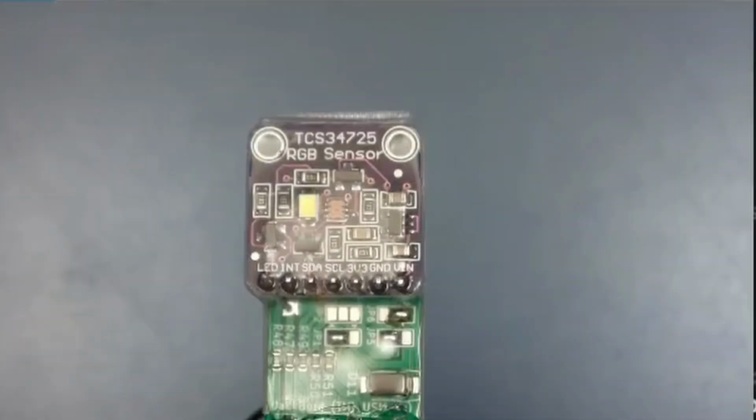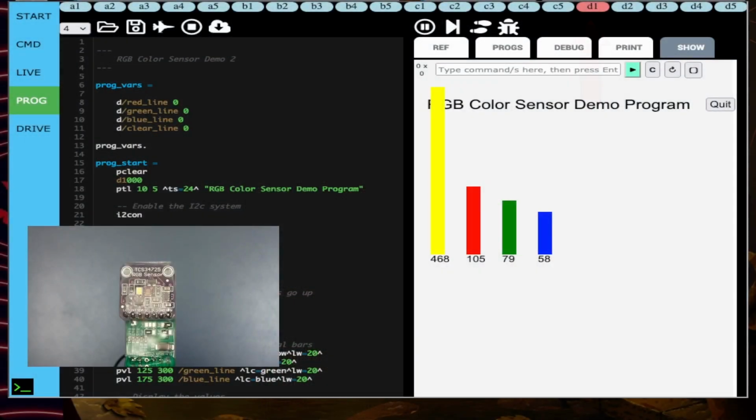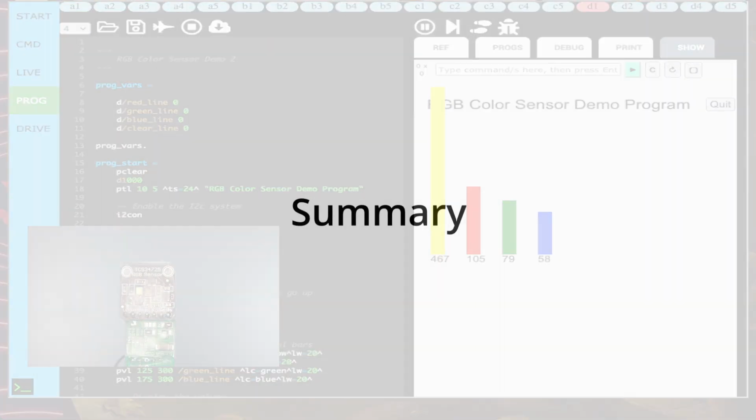The sensor's LED light is located right next to the sensor itself, and in our case, it's controlled by port pin D1. If I want to turn it on, I need to turn on port pin D1, and when I do this, the light turns on. And likewise, to turn it off, we turn port D1 off. There are some instances in which you need the light because the ambient light isn't good enough for detecting colors. In these cases, you turn on the sensor's own light.